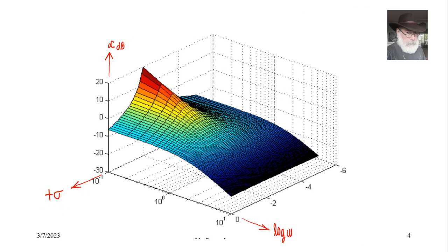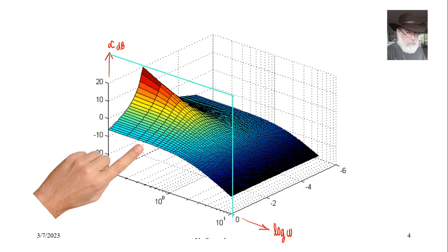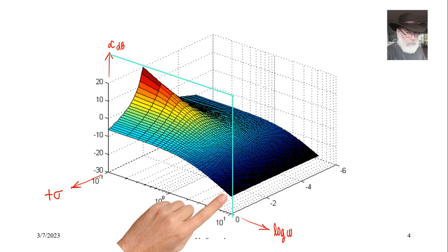Look, in this plot, we visualize the decibels contribution of that transfer function at any complex frequency on the complex plane. s is equal to sigma plus j omega. In particular, the intersection of that surface with our paper, that is represented with those light green lines, is the amplitude Bode plot that we're looking for.